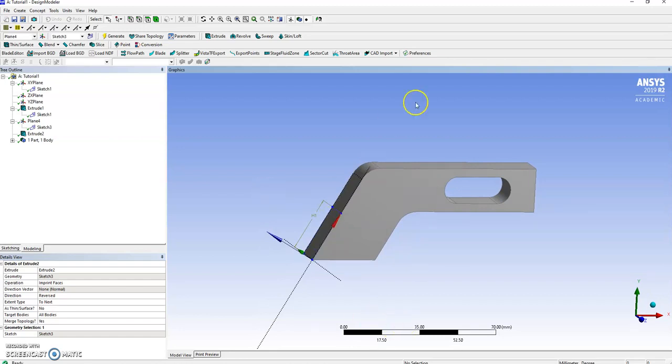Next stage, well, import it into the actual mechanical modeler, the actual finite elements, and do all the meshing, apply the boundary conditions, well, choose which properties we want to actually analyze, and obtain and solve it.